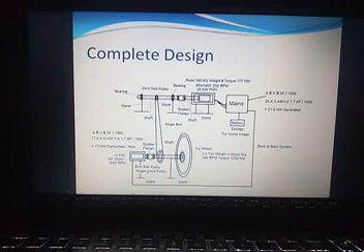The cost of this system is 1 crore per megawatt. In this way, in 1 megawatt we will be generating 24,000 units, that is 24 megawatt hours every day. So we will be generating 79 lakh 80,000 units every year. And if we are in a position to sell at the rate of 50 paise or 1 rupee, we will be earning nearly 80 lakh rupees every year.